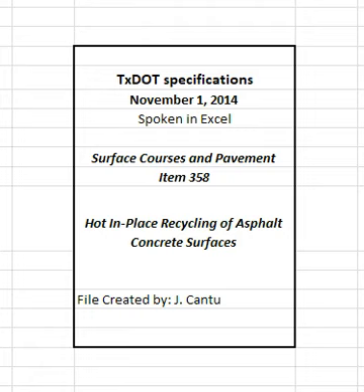4.3 Pavement heating. Heat the existing pavement without charring the pavement surface and without producing undesirable pollutants. Maintain a minimum temperature of 200 degrees Fahrenheit of the material immediately behind the heater. Uniformly heat the pavement surface across its full lane width such that cold milling of the pavement surface does not occur. 4.4 Pavement milling. Mill the existing pavement to the required depth and width as indicated on the plans. Do not disturb the underlying material in the existing roadway when recycling.